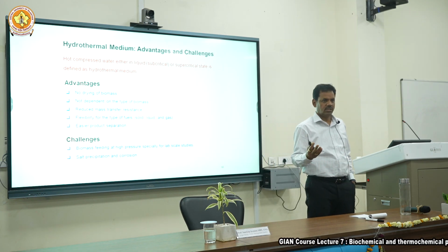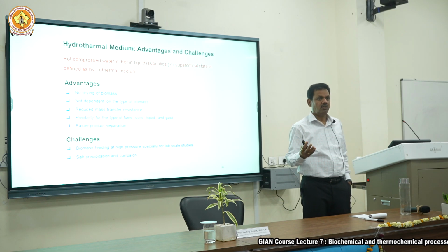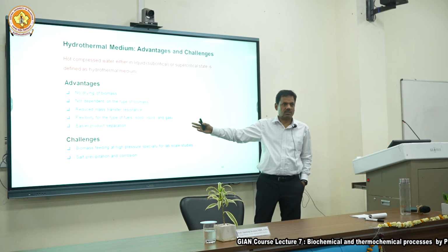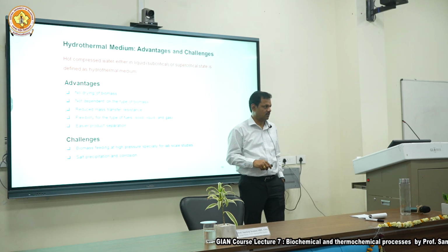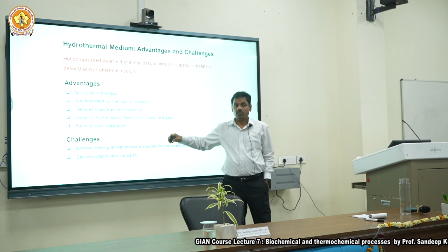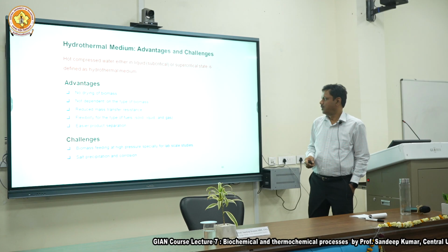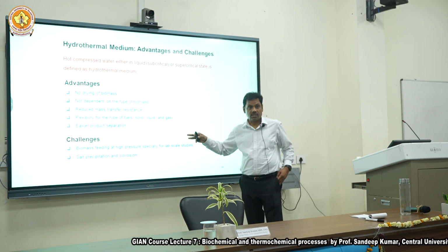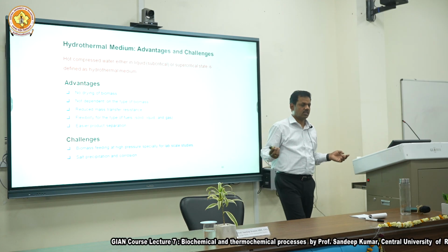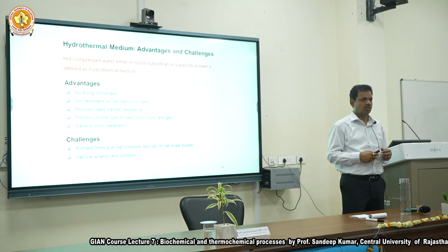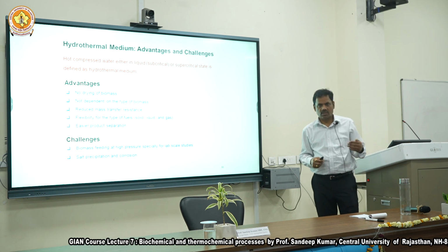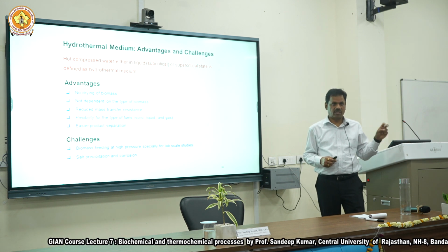Pyrolysis, you do carbonization to make biochar. You can do pyrolysis to make char in the presence of water. You can produce liquid biocrude or bio-oil in the presence of water. You can gasify in the supercritical range at higher temperature, and produce a gas mix of carbon monoxide, hydrogen and so on. So what I am saying is that water is not always bad.